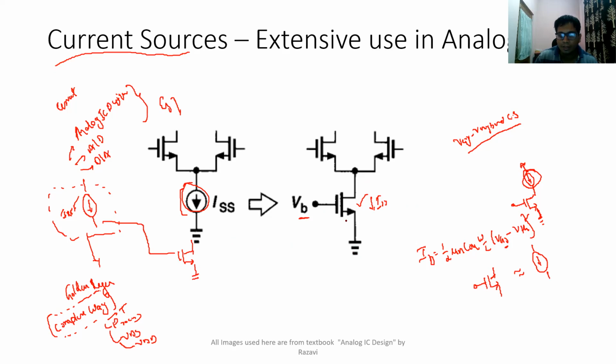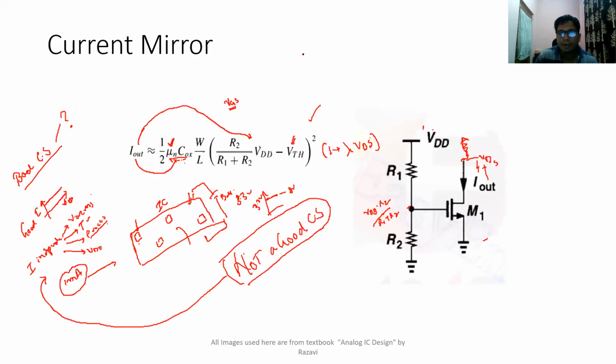In other words, we design a single current source for an entire IC. We design a golden reference, and it requires a lot of effort. By putting in a lot of effort, you design a golden reference, and wherever this reference is required, you just copy it. For example, in the differential amplifier we just saw, it required a current source. So we will simply copy this current here instead of placing a current source there, and it behaves as if the real reference is present here.